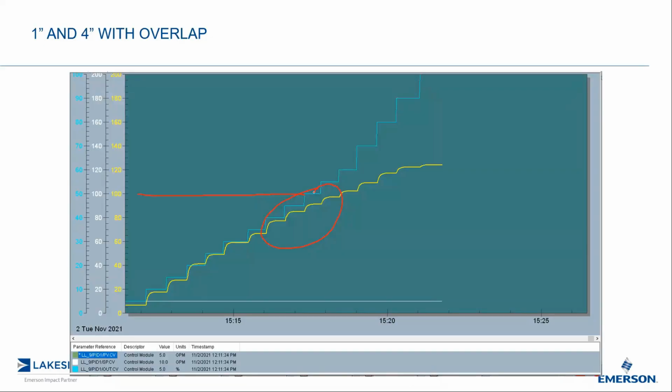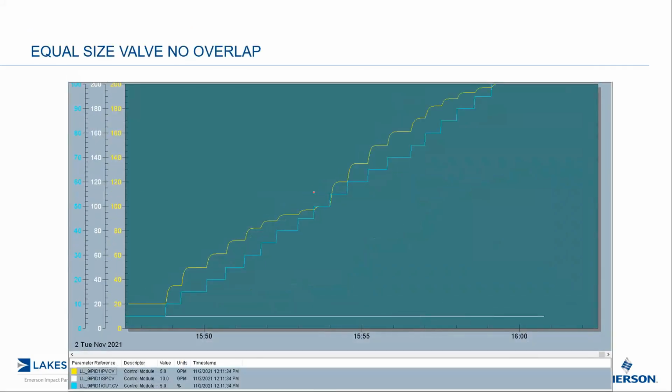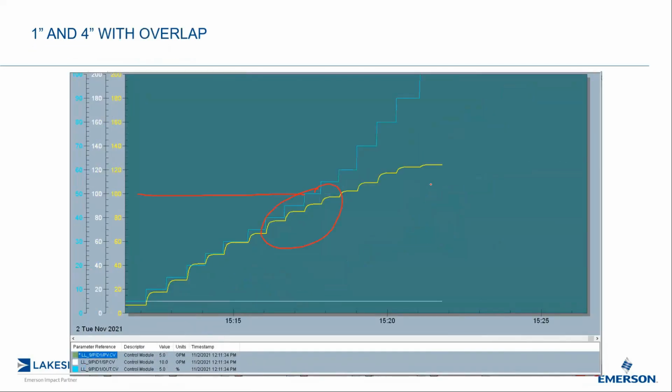And what we're trying to do here is to make the process as constant as possible. So therefore, we don't have to worry about our tuning being off, being at one end or the other end. If I go back to here, obviously I could tune it here, but then the tuning would be very different for here and vice versa. So that's what we're trying to do here: to achieve a constant response throughout the entire range.